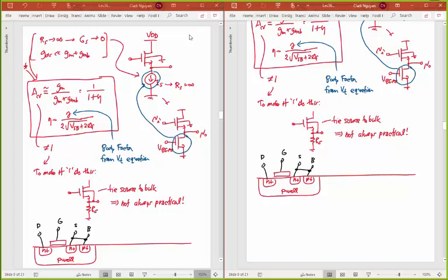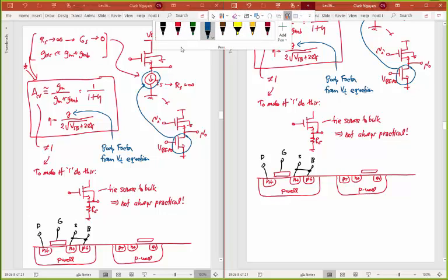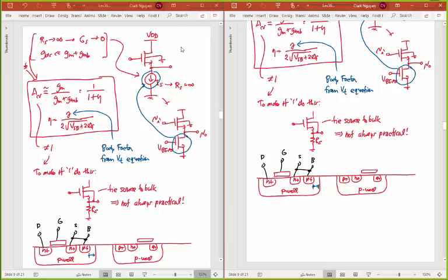The trouble with this is that if you wanted to do this for all transistors, the next transistor, that's an NPN transistor, would have to be in its own P-well. And so I could have a transistor here that, say, has its P plus there, has N plus, another N plus, and another gate there. And if you want your transistors to have their own P-wells, then you're going to have a minimum distance here.